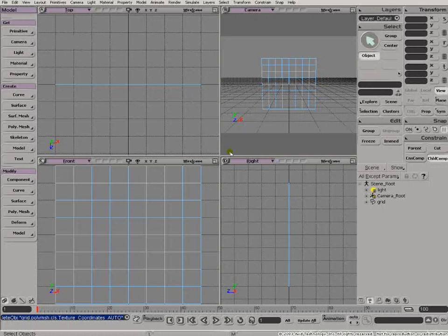Okay, so we've just been through our basic noise and turbulence nodes, the two nodes that we're going to be using for building up more complex natural phenomena textures. Before we go too much further, let's have a look at three basic techniques for working with these nodes. First thing we're going to look at is parameter distortion, using noise and turbulence nodes for distorting the parameters of other